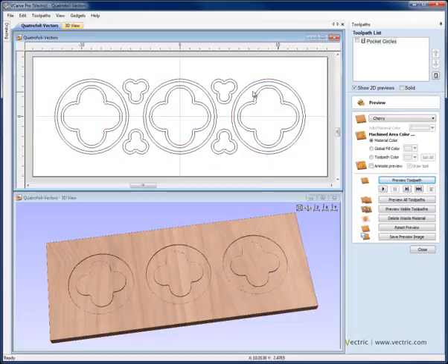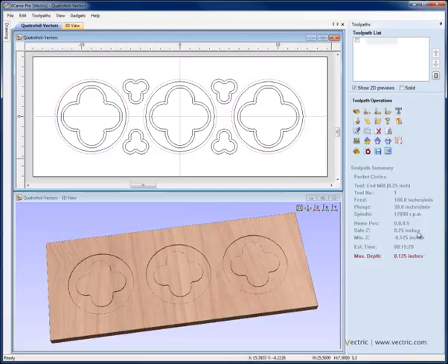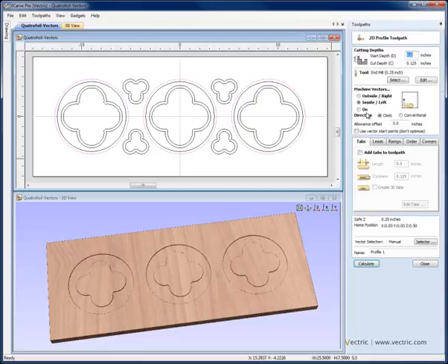Next, I want to take each of those circles and profile around them. So I'm going to, inside of them, so I'm going to select each of the larger circles. So you just click off to deselect, select those 3. We'll close the preview here, come to the create profile toolpath, and I've already machined these down 1/8 of an inch. So I'm going to put in a start depth of 0.125, and the cut depth I want to be an additional 0.125. So the total cut depth will be 0.25, but that's based on a start depth of 0.125 and then this additional cut depth of 0.125.